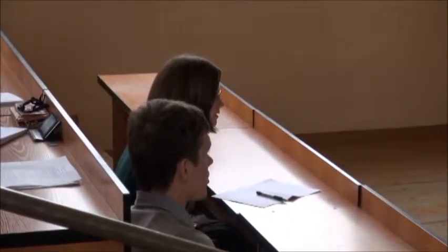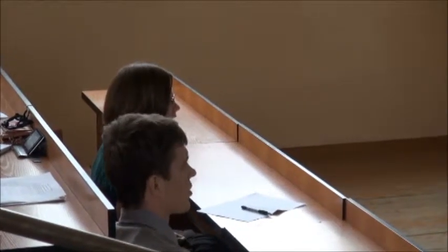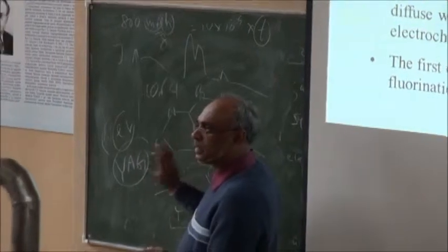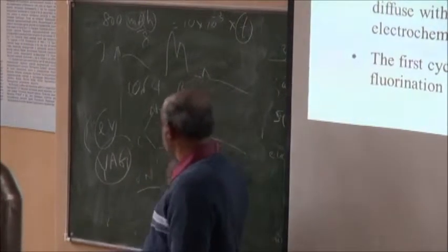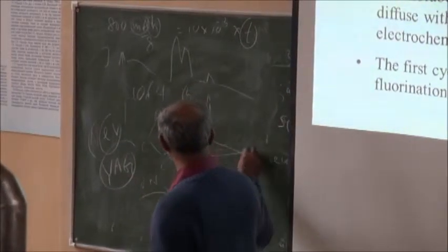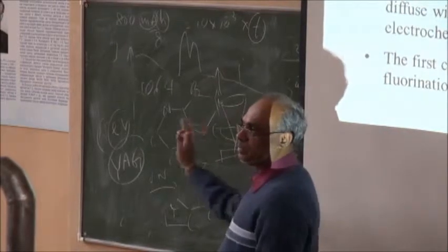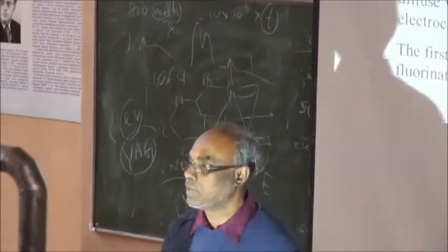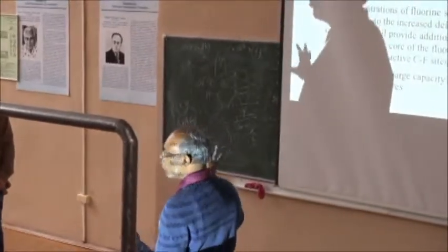Do you use a CO2 laser? No, the YAG laser, the 1064 pulsed laser. These are nanosecond pulses. When we break the bond, we introduce the gas species from plasma. But you break it on a big surface? Yes, we are scanning it. Typically the sample is like that, and we move the laser back and forth. Initially Rom was trying with nitrogen, but it didn't give good results. Now we are introducing ammonia, which has more reactive nitrogen.